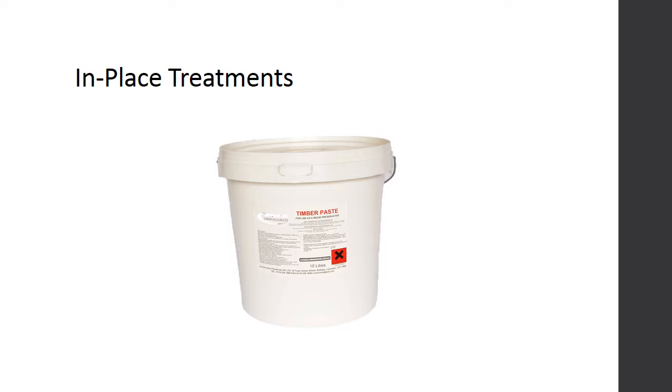In-place treatments are another common preventative maintenance technique applied to timber elements. Surface treatments, paste, and fumigants are three types of in-place treatment that are frequently used. On-site fabrication of timber bridge components typically results in breaks in the protective plant-applied preservative barrier. Pile tops, which are typically cut to length after installation, specifically need reapplication of an in-place preservative to the cut ends. Likewise, the exposed end grain and joints, which are more susceptible to moisture absorption, and the immediate area around all fasteners, including drill holes, require supplemental on-site treatment.